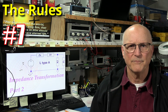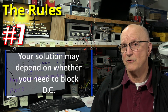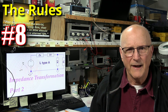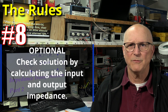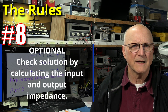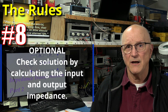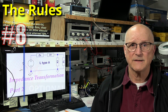Rule number 7. A choice of solutions may depend on whether you want your network to block some DC component of the source signal or not. Rule number 8, and this is an optional one. You can check your work by determining the input and output impedance of the circuit with the intended source and load impedances. They should show up as the complex conjugate of both, where either or both are complex.